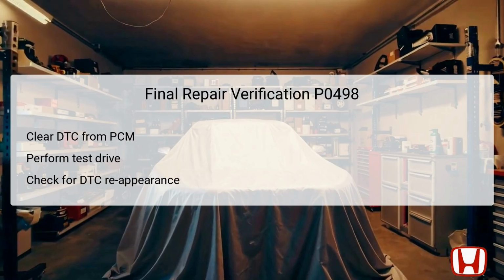Once all necessary repairs and replacements are made, verifying the effectiveness of these repairs is critical to ensuring the issue is resolved. Start by clearing the DTCs from the PCM, which resets the system. After clearing the codes, you should perform a test drive under various conditions, allowing the PCM to monitor system performance. Pay attention to any abnormal behavior or error messages during the drive.